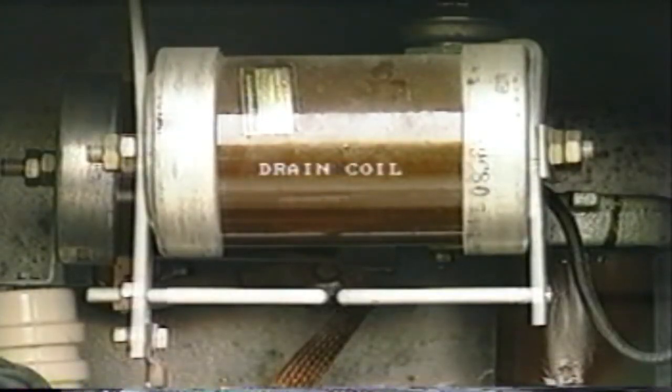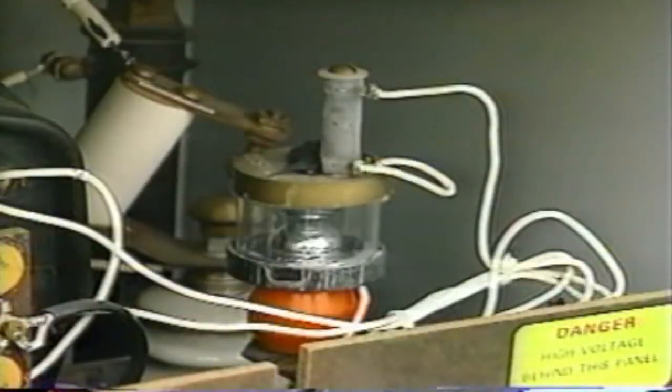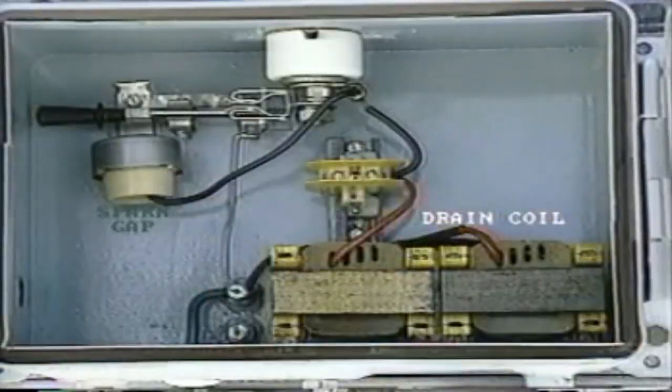The drain coil is made of very light wire and therefore cannot withstand high current or survive high voltages such as lightning transients. This is why the lightning arrestor is installed here. It may be a gas tube protector similar to the type used on telephone circuits or on pilot wire protection. Alternatively, the lightning arrestor could consist of a simple spark gap, such as a spark plug.